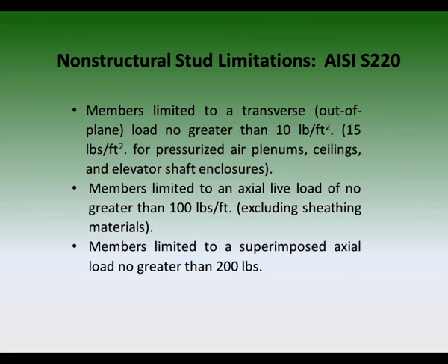AISI S220 places limits on what can be called non-structural. As you can see, it's set at 10 psf for a load perpendicular to or out of plane from the wall. Some special locations, such as pressurized plenums, have higher allowable loads. Members are also limited to axial live loads of 100 pounds per foot, or a point load exceeding 200 pounds. Anything above these limits needs to be designated as a structural application.